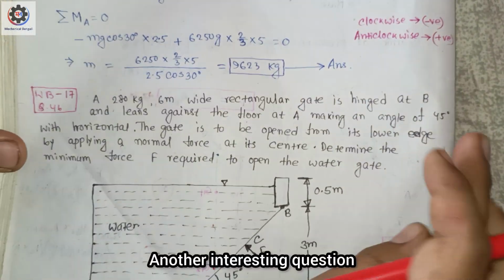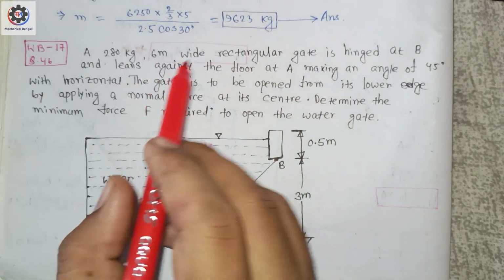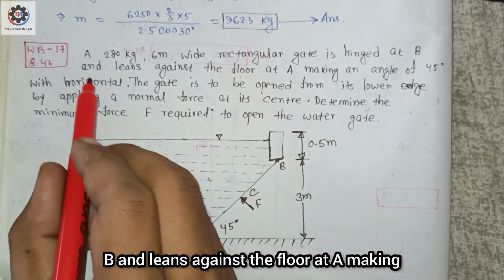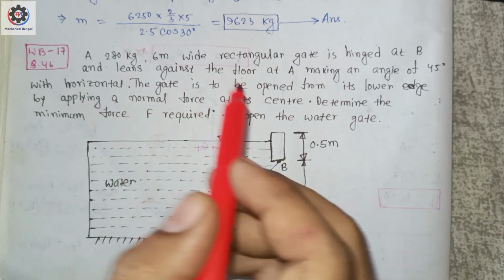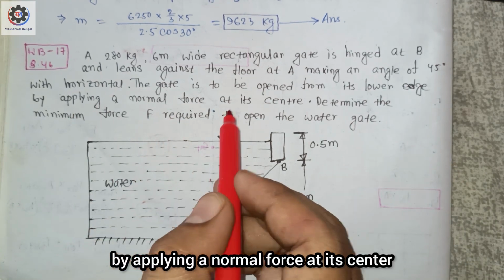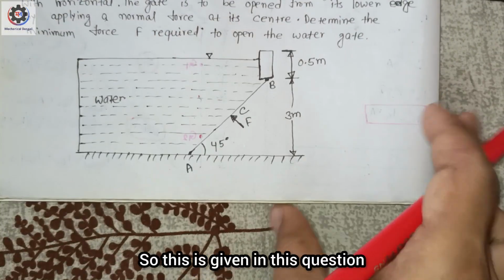Now another interesting question. So try to solve this on your own, but I solved this question in this video. A 280 kg, 6 meter wide rectangular gate is hinged at B and leans against the floor at A, making an angle of 45 degree with horizontal. The gate is to be opened from its lower edge by applying a normal force at its center. Determine the minimum force required to open the water gate. So this is given in this question.